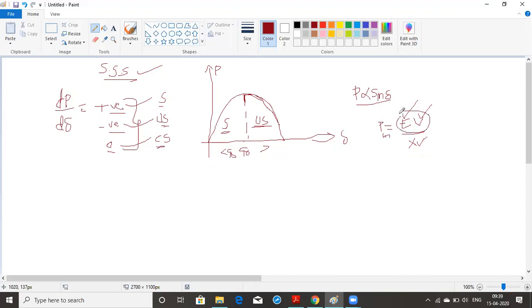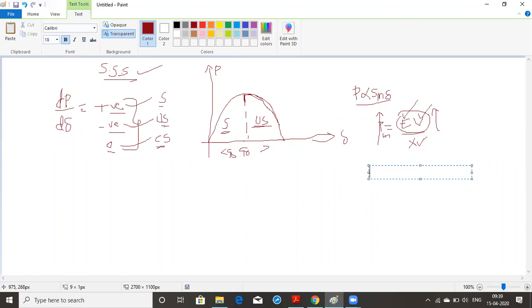You can see if you are increasing the internal EMFs of the machines, either the excitation voltage or the terminal voltage of the motor, and the excitation voltage of a generator, then the maximum power is going to increase. That means we have one method, called increasing the internal EMFs. If you are increasing the internal EMFs, what happens?